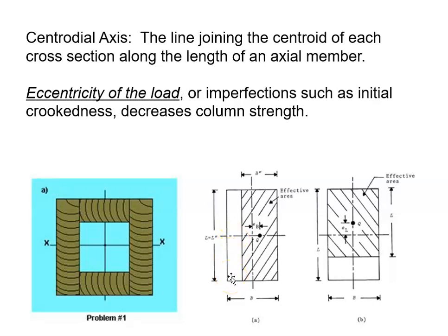And therefore, the line of the axis there is eccentric. It's eccentric because it is not straight. Or if you had a timber column, for instance, it could be an imperfection that does this. It could be a crooked timber. And when this load is not perfectly centered, when the loading does not run straight down the center or agree with the center of the column, then it is eccentric.